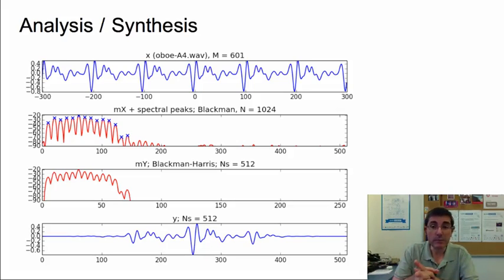But we have one problem, and that's the problem of overlap in the process of synthesizing. The Blackman-Harris window requires a big overlap. If we want to generate a time-varying signal, the overlap of a Blackman-Harris should be very high, even bigger than 1/8 of the window length.